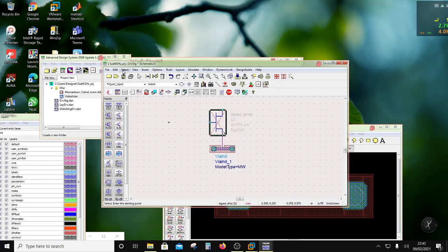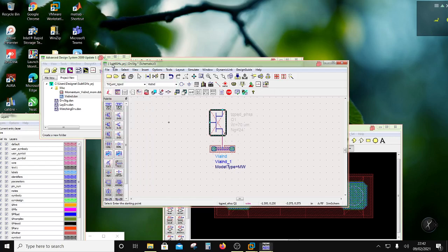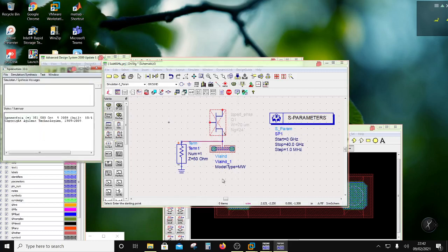So if I take an S parameter simulation, so if I go to find the S parameter simulation, let's see what this looks like up to 40 gigahertz. I'm going to go from DC. This is already simulated, right? So to save your time, I simulated this, and let's say I'm going to do 1 megahertz. This is an adaptive model, so it is going to interpolate. And then I'm going to look at, let's say, terminal, and I'm going to look at the single port simulation, right? So I'm going to just look at what kind of inductance I'm seeing at the ground.